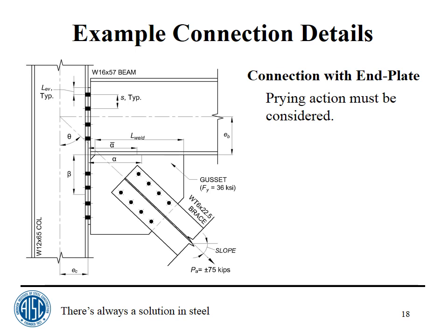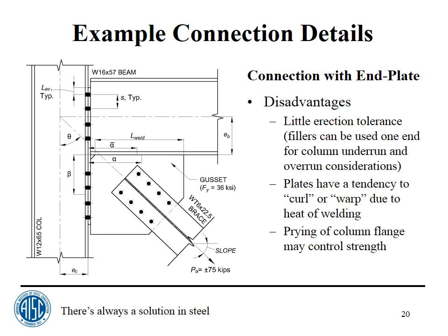Then when you weld this thing, the plates themselves are going to curl up a little bit, maybe compromise the distance between the column flanges from one side to the other. Well, the short answer to the question is not to my knowledge. There's nothing published that I know of on how you should exactly detail this.